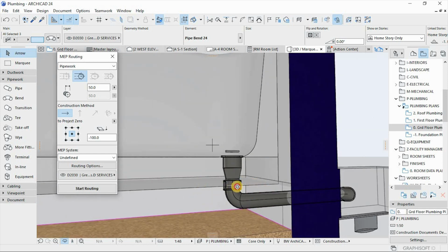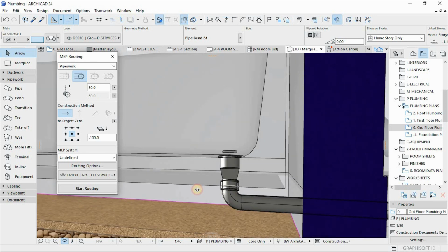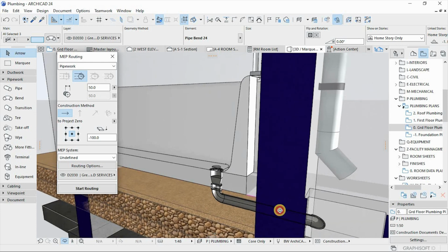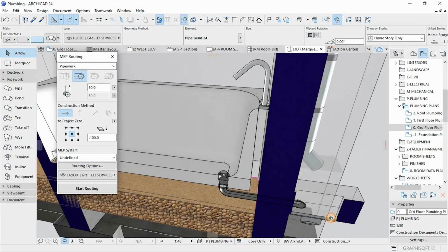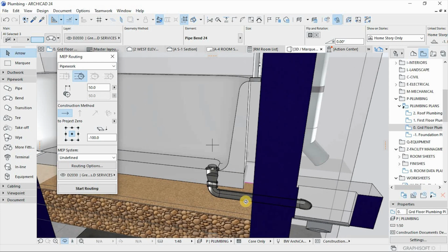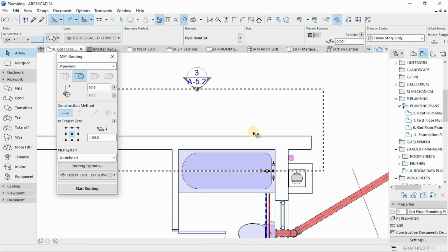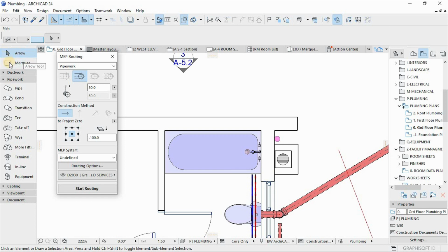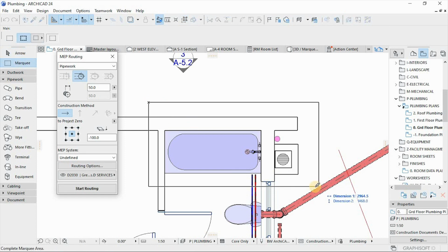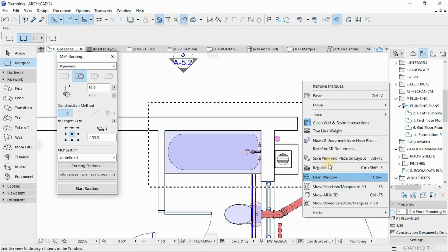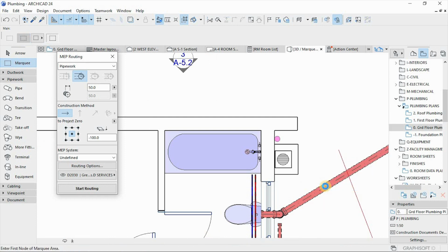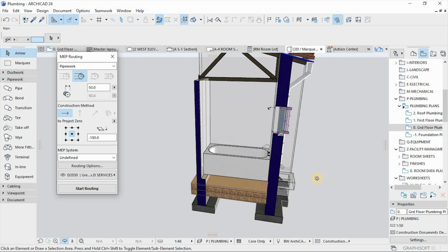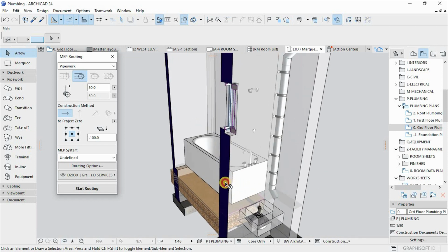tab basket. What we need to do is to introduce the overflow riser. The overflow riser, I'll connect it on this pipe. Let's go to the ground plane. Then I'll do this mark Q like so, then show selection and mark Q. Let me hide these walls.